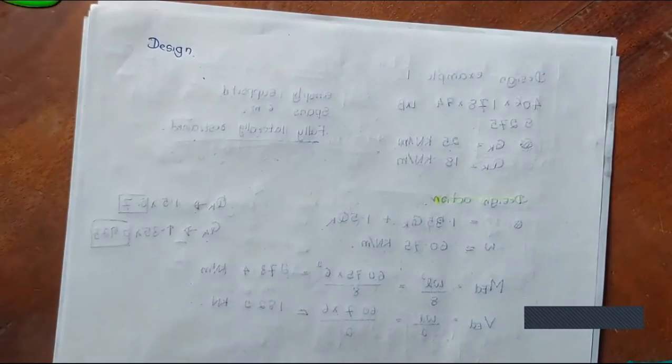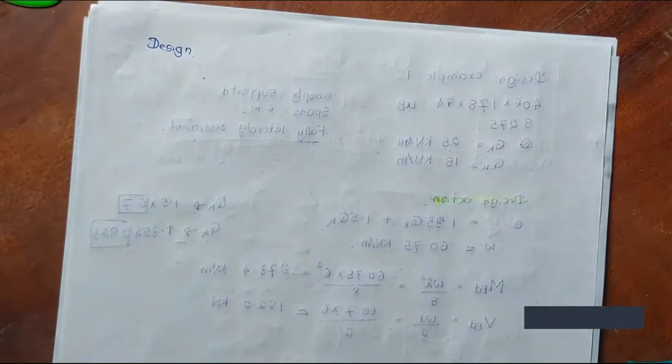We have shear force and bending moment. So anybody would know we should check whether our beam can take this bending moment and shear force, right? So probably you have to check the shear resistance and the bending resistance, but depending on the section it changes. That's why we define what this section is, right?